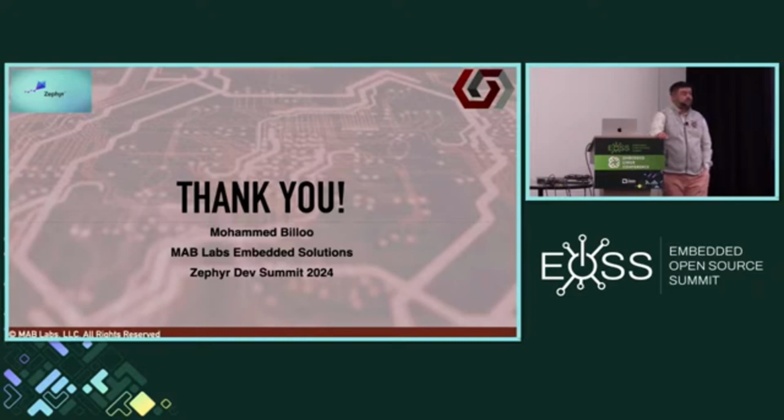I've got a slight question or comment on OpenAMP, the protocol there. Are the messages fixed size? I think they are, I think they're well defined. Yeah, and one of the challenges that we've run into is that you want a version of it that allows flexible sizes for things like a network coprocessor that you're using OpenAMP to talk to.